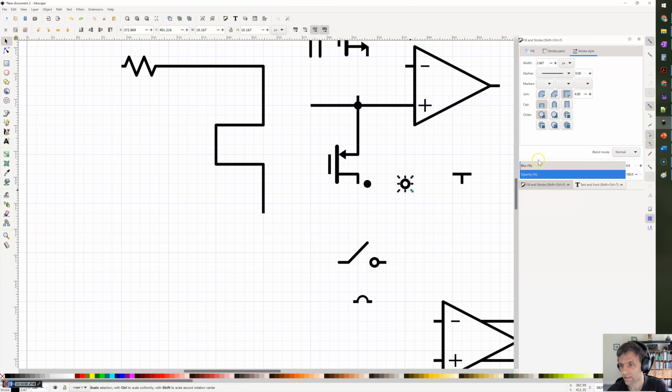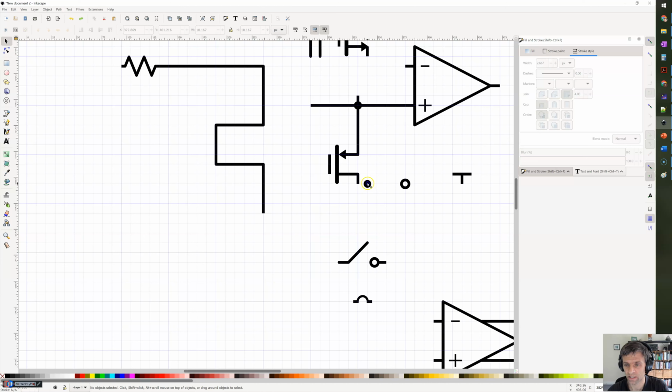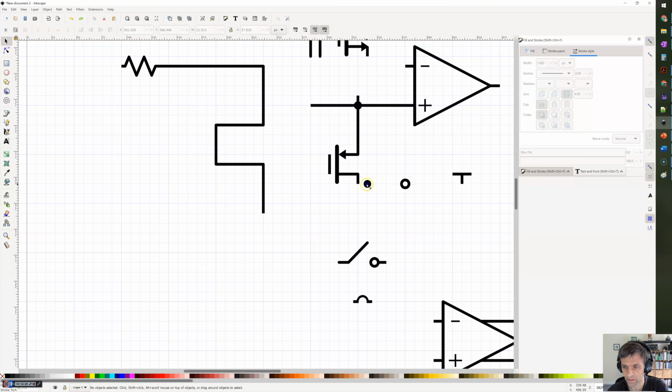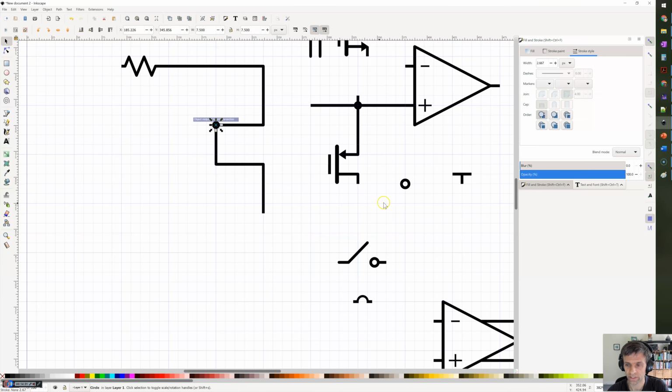So when I'm dragging these kind of shapes around, I turn off this selection, and instead I activate this one down here, which snaps some other points of the shape to the grid. And in particular, I activate this one here, which says snap centers of objects to the grid. So now that's going to give me my more desired behavior here, right? Where I can, oops, grab the wrong one here. I'm going to grab this one. Now I'm snapping the center to the grid. So that's going to be much better for dragging circles around, right?